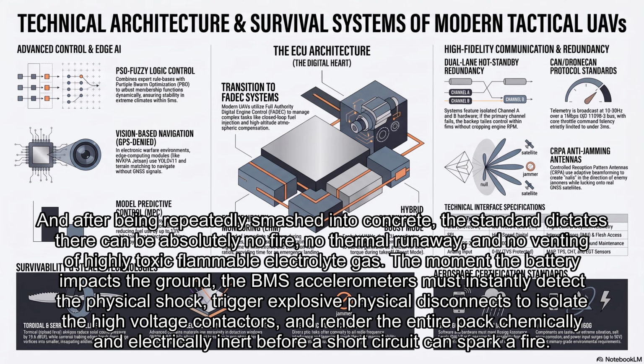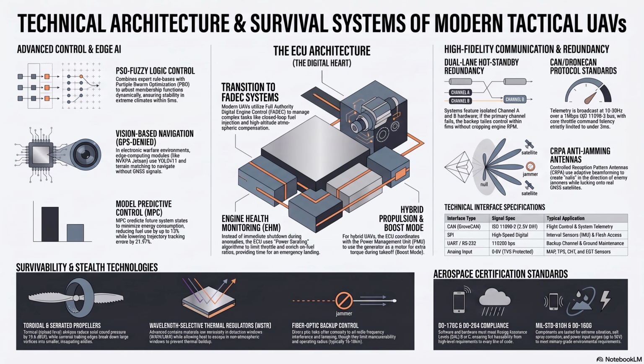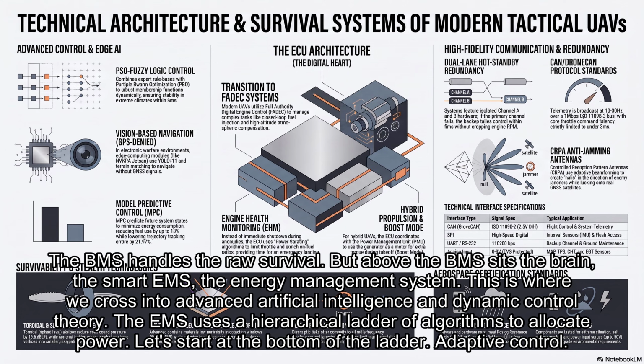The moment the battery impacts the ground, the BMS accelerometers must instantly detect the physical shock, trigger explosive physical disconnects to isolate the high-voltage contactors, and render the entire pack chemically and electrically inert before a short circuit can spark a fire. The BMS handles the raw survival.